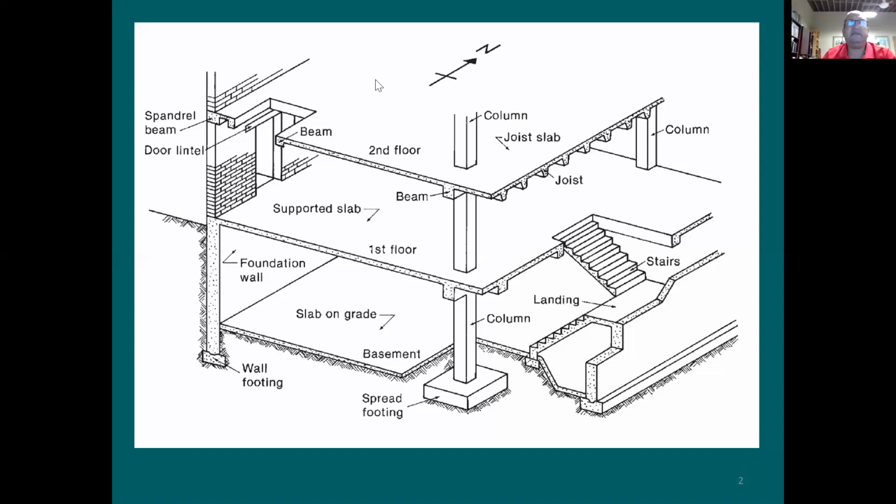Now what happened in this floor system, let's say, this is not the only column supporting the slab, right? On the top, we have other columns and some walls. So I'm gonna say this column here and this column, maybe another column in some other place. This load, which means the weight of this slab and the live load, like the occupancy load, when you have furniture and you have people walking on it, it's gonna be all supported by this wall and supported by this column, supported by this column. Distribution is gonna be based on the stiffness or tributary area, if you like. So for each one of these elements, you need to figure out how much load is gonna be going there.